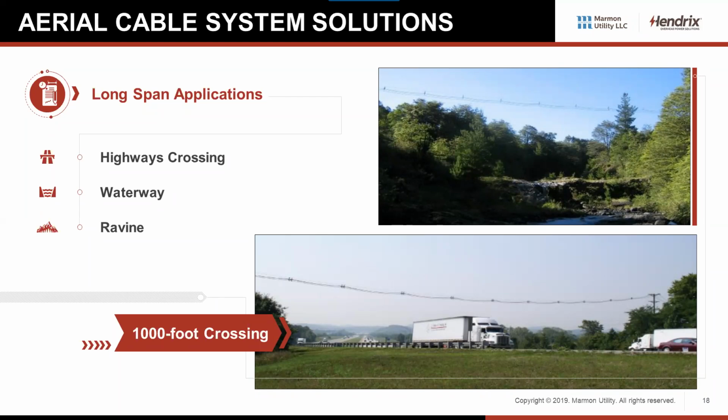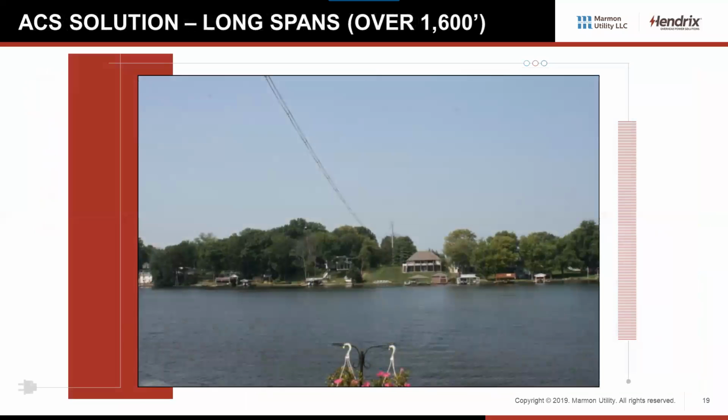So I don't have to worry about what size conductor I'm using. I just have to adjust the size of the messenger. So we can run spans, I don't want to say as far as we want, but we can meet whatever requirements there are, and we don't have to worry about increasing the size of the actual conductor.